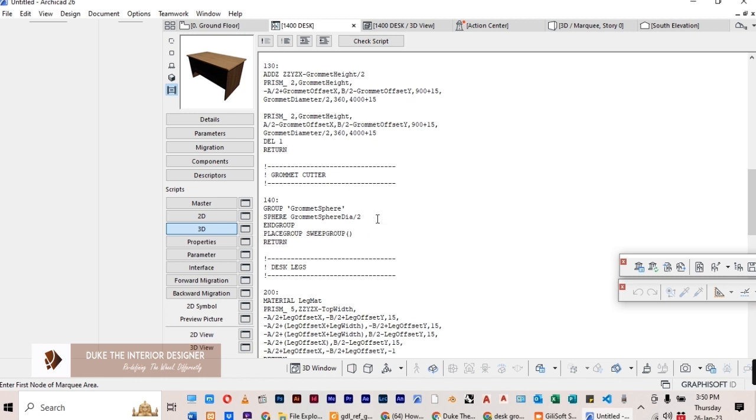The first thing that we need is the group that you're stretching. Don't forget to copy the apostrophes. Then you ask yourself, are you stretching it to what side? Is it the X value, the Y value, or the Z value? For us, we are stretching it towards the X direction.